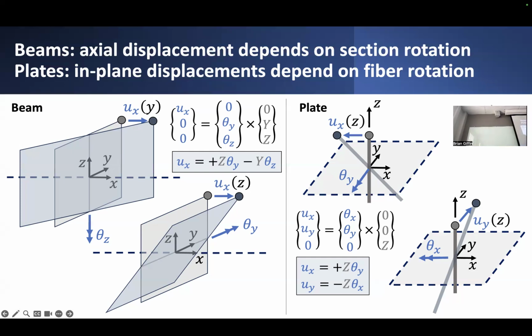And it turns out, it's a rather general statement, that this rotation vector taken in cross product with the actual position of this point, measured assuming that it's basically just a y and z coordinate that I'm looking at, and assuming that the x coordinate I can just neglect or say it's 0, the cross product of this rotation vector with the position vector of some point on this surface gives me precisely the description of that kind of axial displacement.